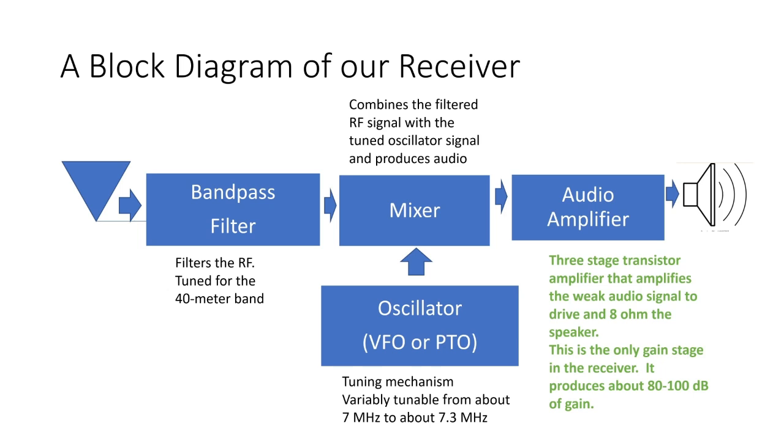if you'll recall, when we talked about the oscillator circuit, we talked about how an oscillator is simply an amplifier with feedback. So a little bit of the output gets back to the input, and like a cat chasing its tail, it starts to amplify, or like a loudspeaker in a PA system. If you get too close to the microphone with the speaker, or it's too loud, it will take off and start oscillating.